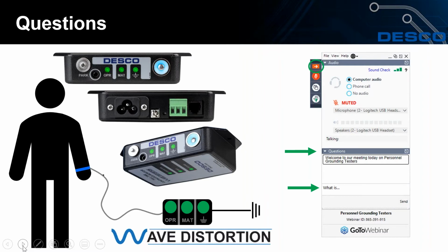Okay, if you're currently touch testing right now, that touch tester has 2 results that you may get. One would be a fail low and the other would be a fail high. As I mentioned before, when you're failing high, that's a high resistance, so I'm going above the upper limit of the tester. However, all wrist straps and coil cords have a 1 megohm safety resistor in there for personal safety, to keep you from getting shocked, if you will.